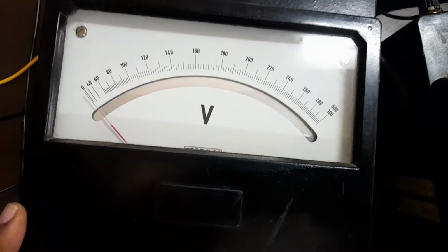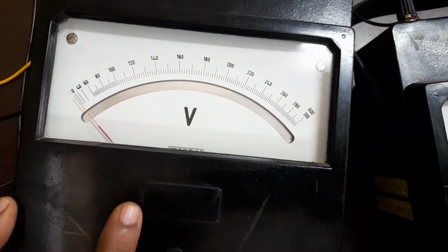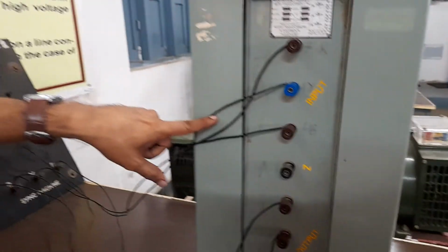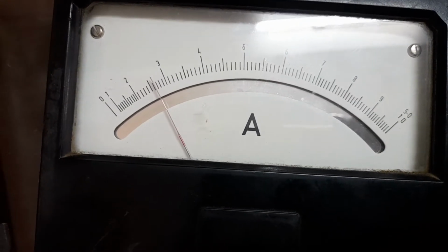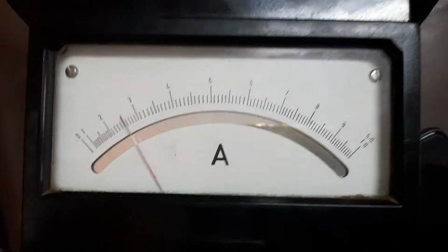And see here, the voltmeter connected across field winding terminals is showing 0. It does mean that the phase sequence of alternator and phase sequence of three-phase supply both are matched. Once the phase sequence is matched, then slowly we can conduct the experiment here. Please observe. After giving reduced voltage, we need to measure the speed again, because we need to run the machine at a reduced speed, something around 1485 or 1490. So before going to that, please check it.